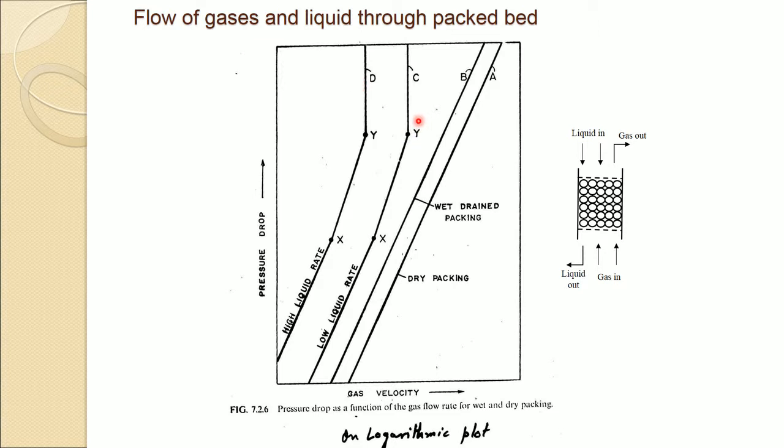So, certainly a blast furnace cannot operate above this, it is an abnormal operation. The problem will come, the liquid metal and slag would be carried out to the upper zone, which is a lower temperature zone, and it will deposit over there and solidify.